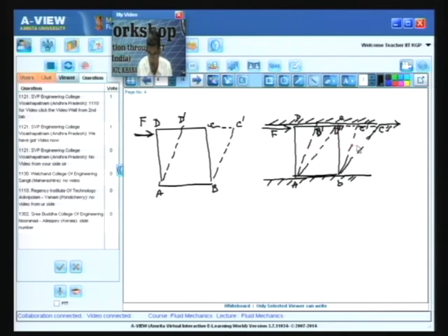That means it goes on continuously changing in its shape, and this continuous change in shape constitutes the flow. The flow is constituted by this continuous change in the deformation or the shape when this force is applied. Moreover, if the force is withdrawn, that is, the plate is stopped, the fluid element will not come back to its original shape; it will remain in its deformed shape. That means it cannot relax to a preferred shape which the solid does. So, in these two ways the fluid and the solid differ.